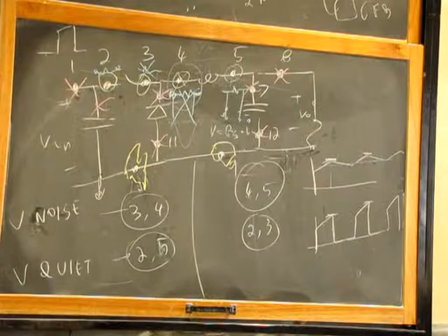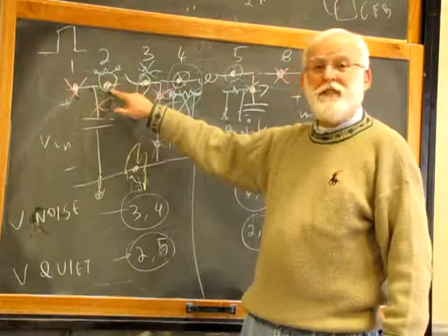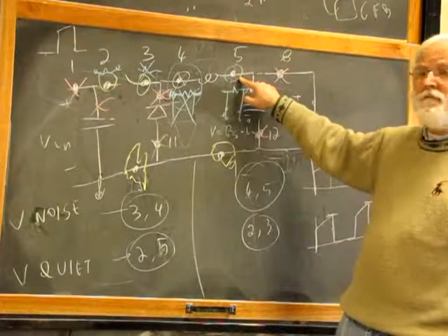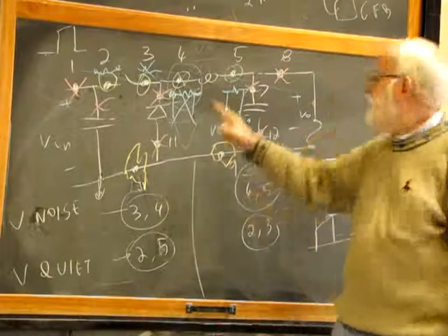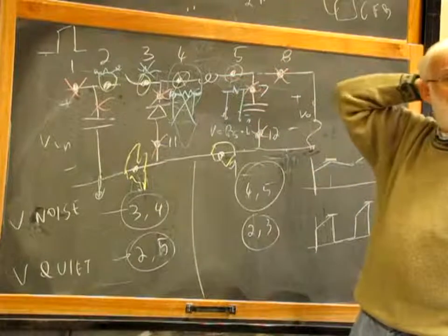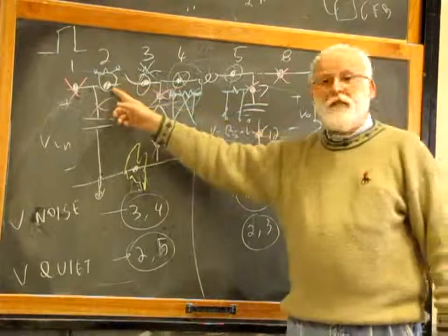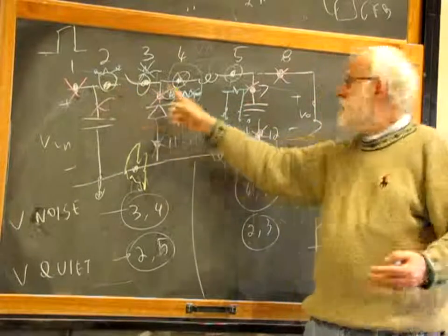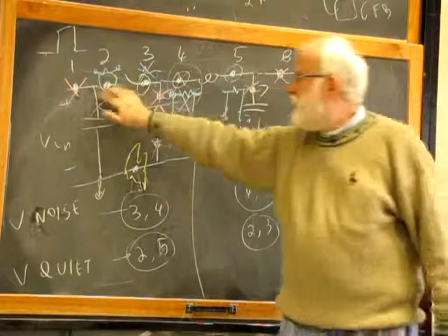2. Why? Because the current is lower, so the power... Sure, that is a very good consideration, thank you. Power dissipation over here, in this resistance, is smaller than over here, because current through the resistor here flows only during D. Here it flows all the time. So if your duty cycle is, let's say, 30% or 70%, the power dissipation over here will be 30% or 70% of the power dissipation you have here. So from the power dissipation point of view, 2 is better.